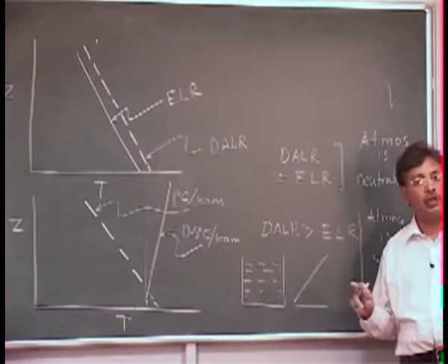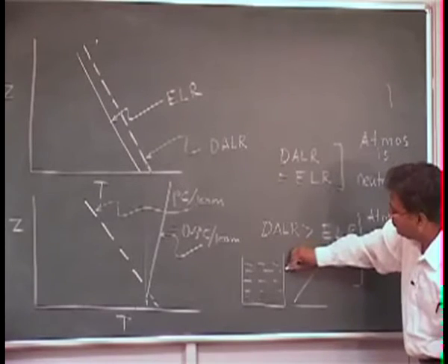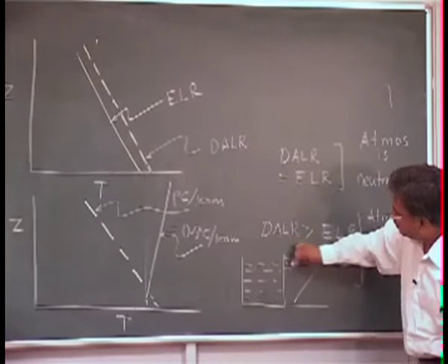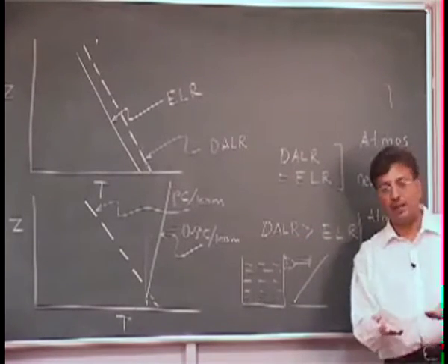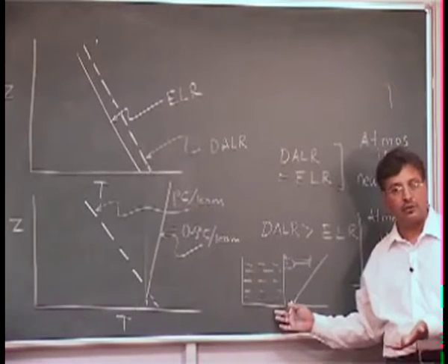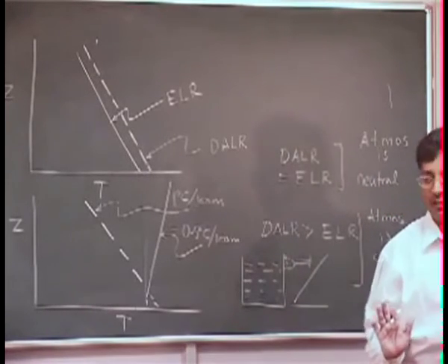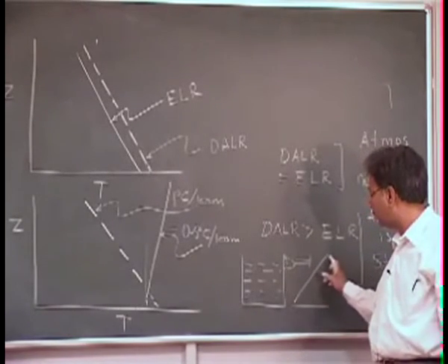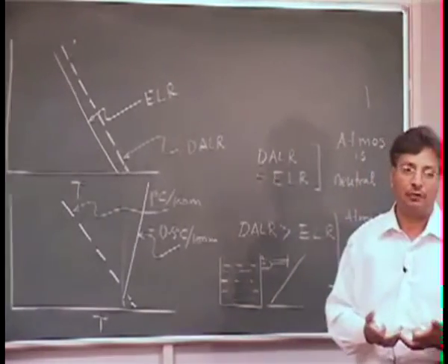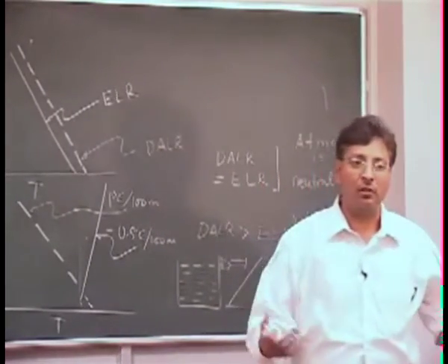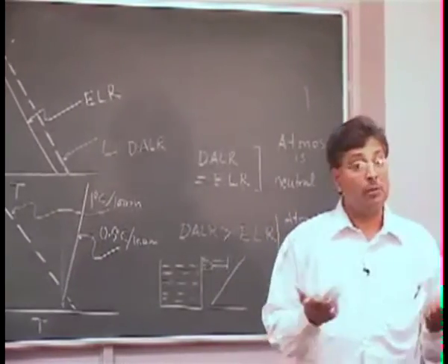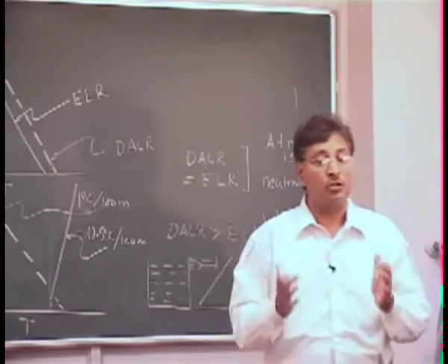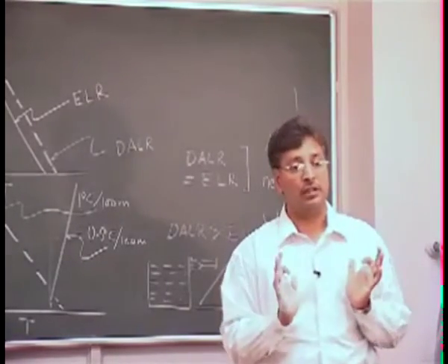So in a way, I am heating the beaker from the top. I put a burner here and I am heating it here. You agree with me? Then only I can have the high temperature here and the lower temperature here. If you are heating the water from the top to get a temperature profile like this, what will the water be doing? Will it be boiling or jumping, or will it be quiet? It will be quiet because there is no convection, nothing going up and down, and there is no turbulence. So water will be sitting very quietly as a stable water.